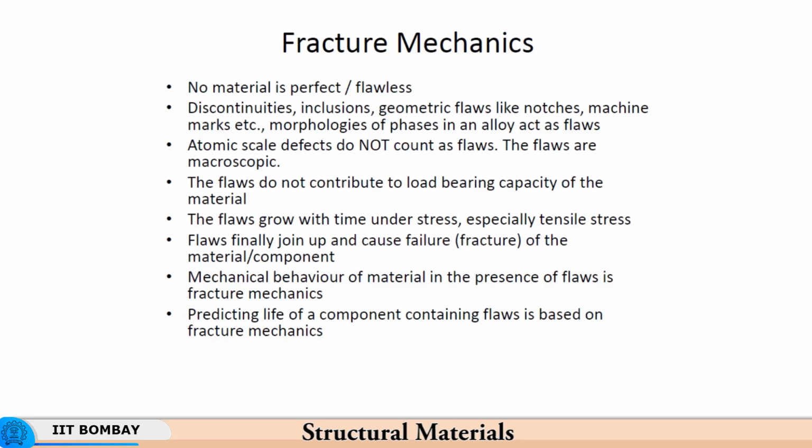Now, different techniques which are used for detecting these flaws have limitations, like the smallest flaw that can be detected by technique A and the smallest flaw detected by technique B could differ. So, you cannot go beyond a certain limit when it comes to detecting flaws. So, essentially you have still some flaws left behind, and these flaws will result in gradual development of cracks or propagation of these flaws, enhancement of these flaws over the service period, leading to a final failure.